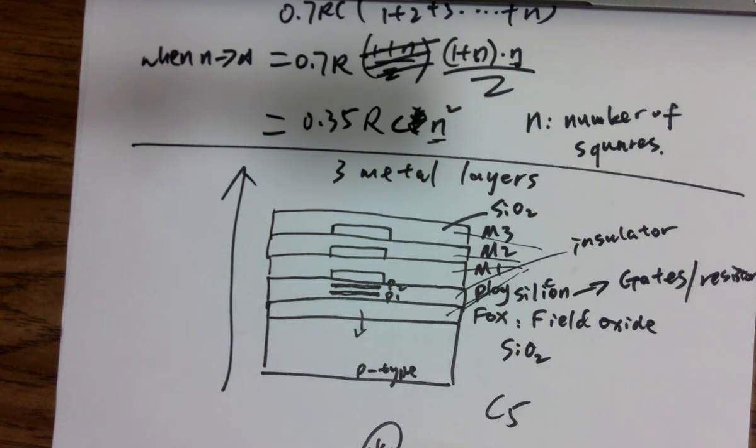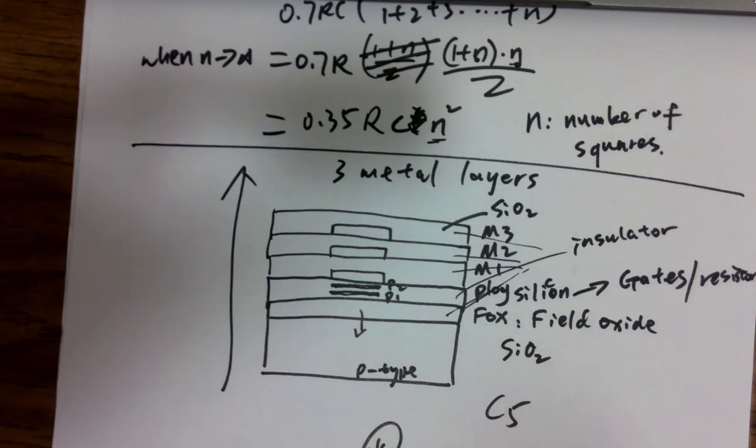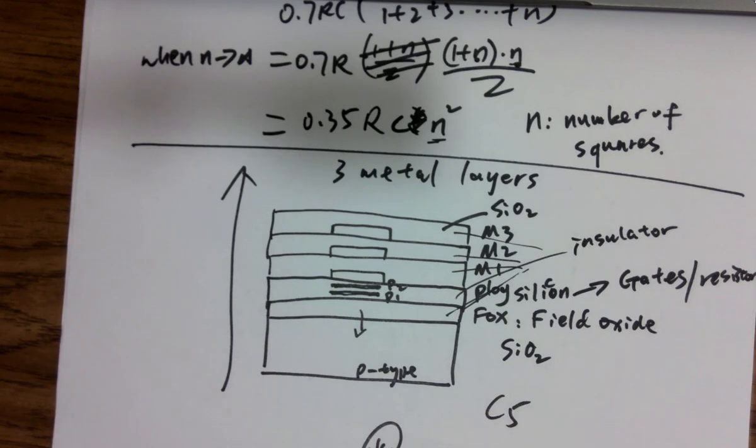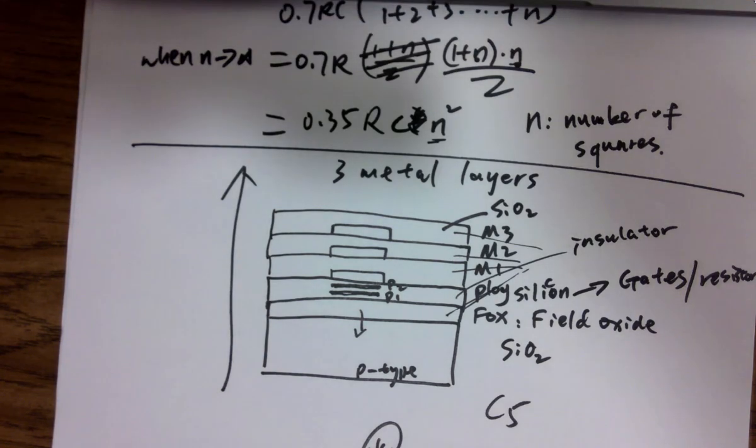You have a lot more transistors in a smaller area, so you do all the routing so they're not shorting to each other. You need to create a lot of layers on the top so you can drill a hole to the top and route it instead of doing this. Does that make sense? Just need more layers, like a PCB design. Same thing. The PCB you are making is mostly just 2 layers. You have a top layer to route traces. If there are short circuits, then you just dig a hole here to the bottom layer and then route the trace